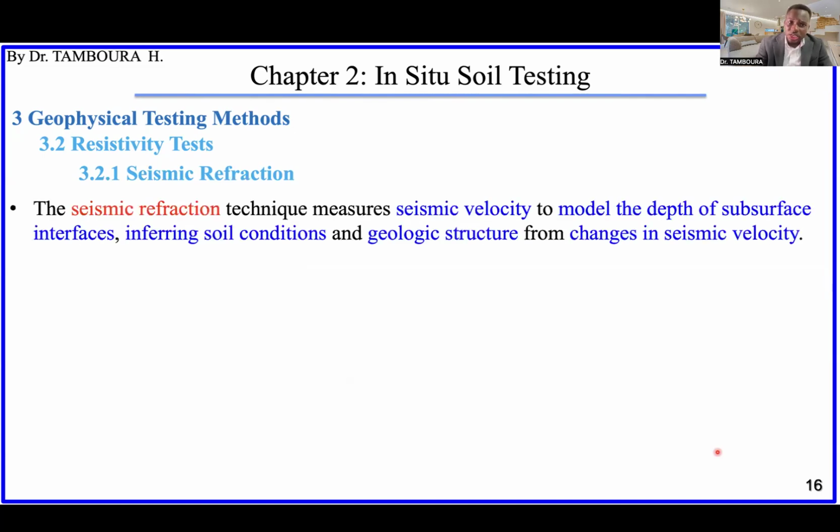The seismic refraction technique measures seismic velocity to model the depth of surface interfaces, inferring soil condition and geologic structure from changes in seismic velocity.